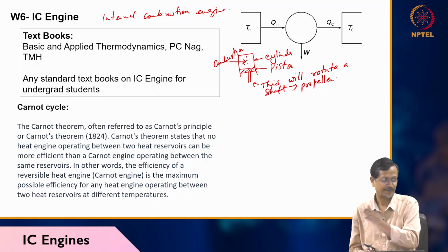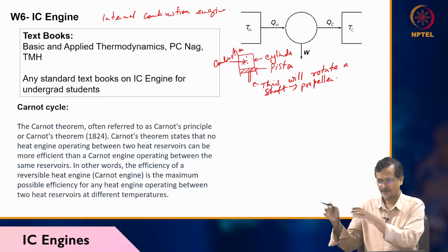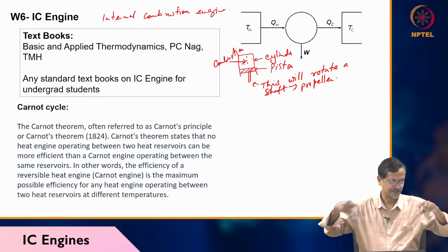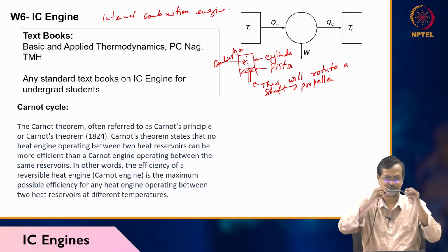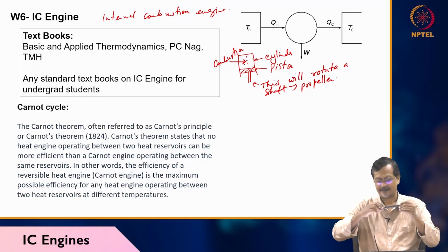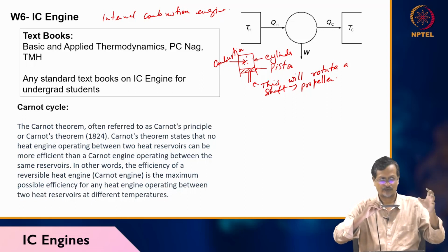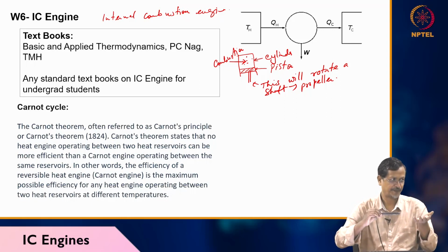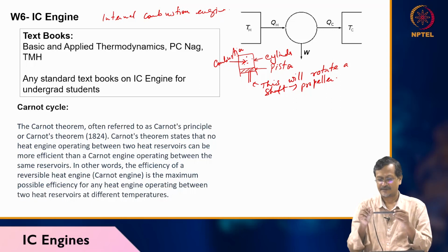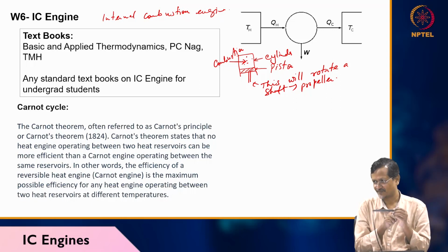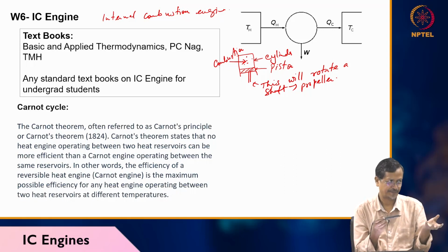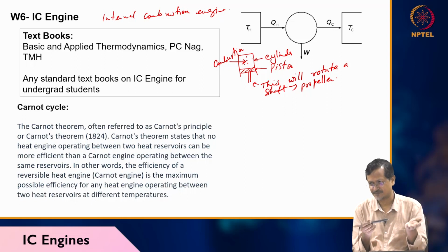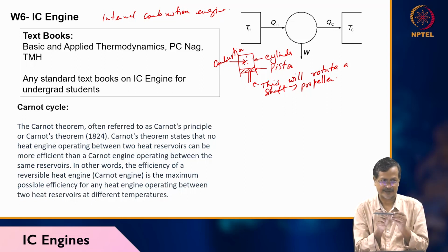Then there will be different mechanisms. One mechanism is that we must have one shaft. Shaft will be transferring torque or power. So engine is rotating this one, this may be shaft, at very high speed, and propeller will have a much lower speed, 100 to 200 rpm. So that means we have to reduce the speed. Engine is producing maybe 700 rpm or 1000 rpm, but your propeller needs 100 to 200 rpm. Sometimes lower rpm also possible. That means you must have certain mechanism to reduce the speed.